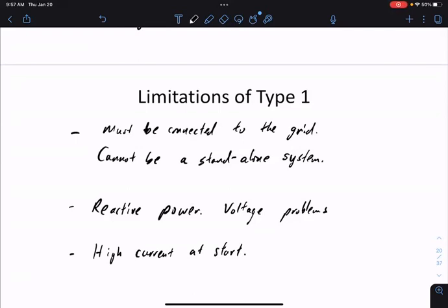So what happens when you have an inrush current that's very large? How do circuit breakers work? Right, they sense current and trip protection. So this tends to not only trip its own protection, but trip other people's protection, because the current you're pulling has to come from somewhere. So then some protection device may think I have a short in the grid, right? So I have a short circuit fault, and that's not great. So this trips a lot of protection.